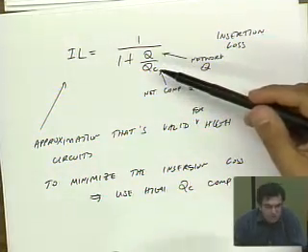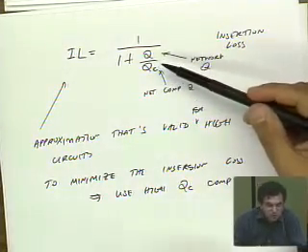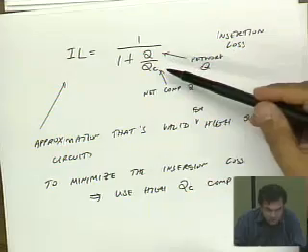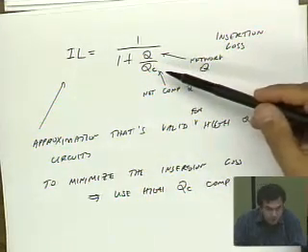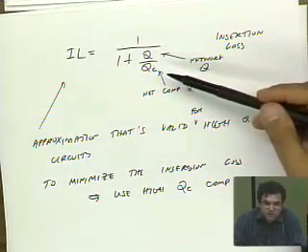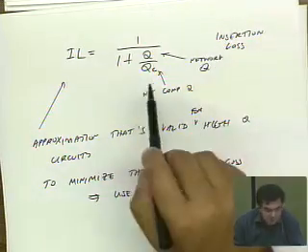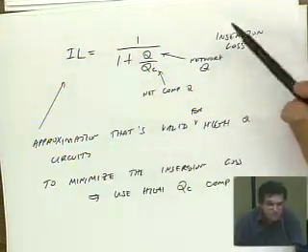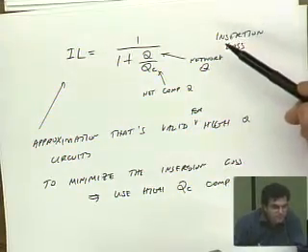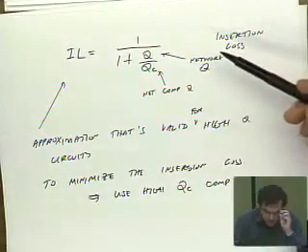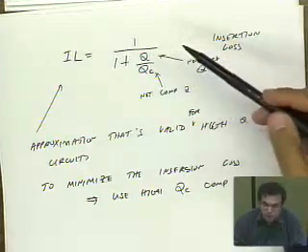It's a marginal difference. On the other hand, if someone says my network quality is 100 and I want to use components with a quality factor of 100, you can see right away that the insertion loss is going to be more than 50%. So it really matters what network Q you're trying to achieve.